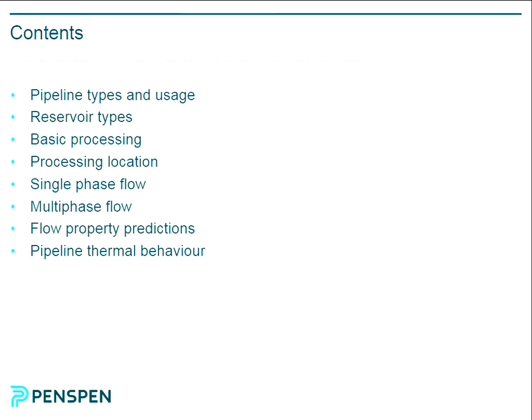And then there are really two considerations about multi-phase flow analysis or any hydraulic analysis: temperature and pressure. If you're lucky, you'll have a system where temperature is not important. But generally speaking, the transportation of oil products is a very strong function of temperature, so pretty much you're always very concerned about temperature. So temperature and pressure are key considerations. There are other considerations for multi-phase flow. So that's what I wanted to cover in the first part, anyway.